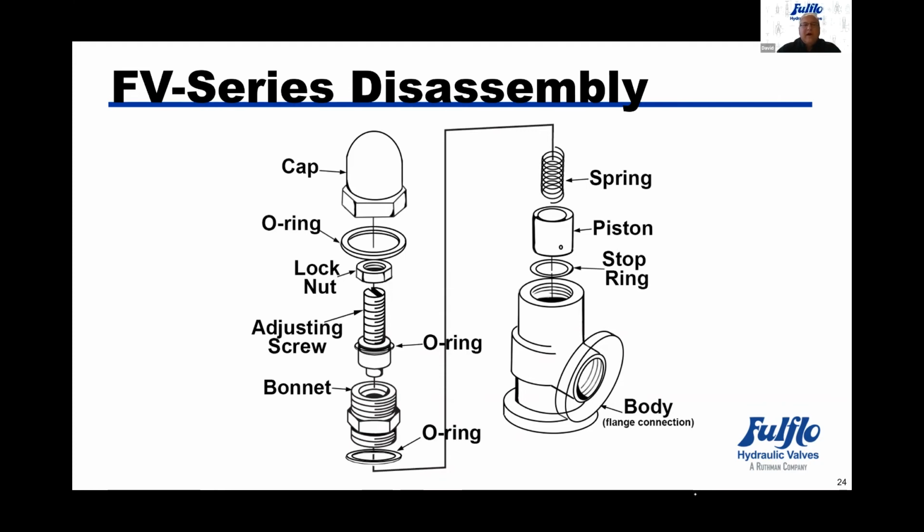So that's what makes this valve more superior over the V-Series valves. On the piston itself, the old design piston had a milled slot on the bottom of the piston, where the newer series valves are flat bottom, but they have a chamfer around the circumference of the piston, which would allow equal distribution of the fluid as the valve is at the set pressure.